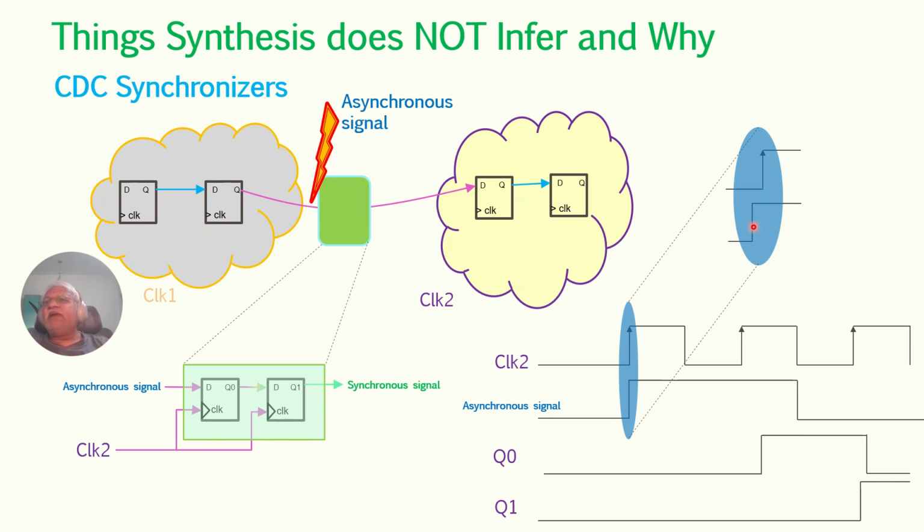At the output of the synchronizer, it has figured out that no signal has come. The asynchronous signal has not changed to logic high, and that is what is fed. So this is called a failure. The synchronizer's reliability is represented by a constant called MTBF, mean time between failure.